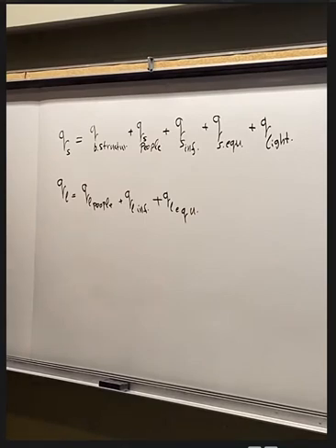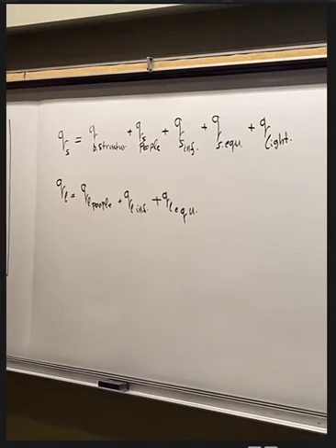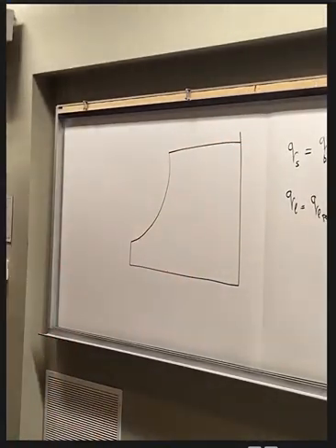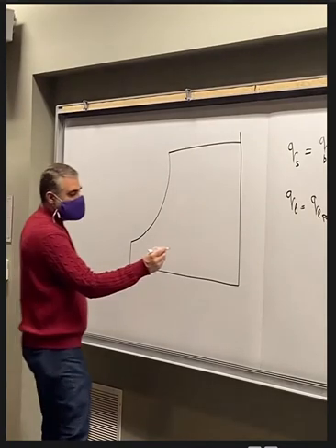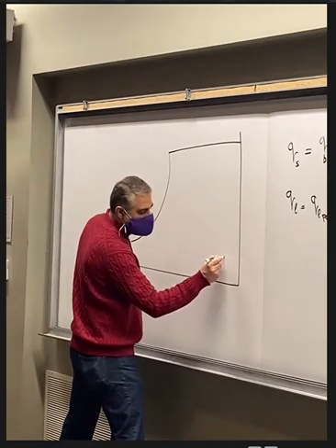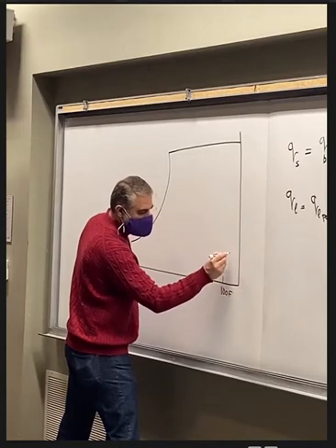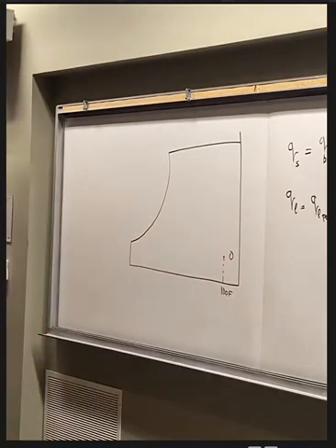So when we find the cooling load in terms of QS and QL, to complete the solution of this question, we have to come up with the psychrometric chart. So the outside air was 100 Fahrenheit and 0.002 humidity ratio. So the outside air, this is point number O.